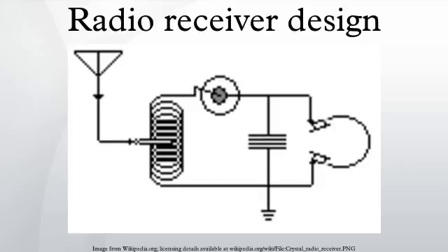Self-oscillation reduced the quality of its reception of an AM radio signal but did ironically make it useful as a CW receiver inasmuch as the beat signal between the oscillation and the radio signal would produce an audio beeping sound. The oscillation of the regenerative receiver could also be an annoying source of local interference. An improved design known as the super regenerative receiver improved the performance by allowing an oscillation to build up which was then quenched, with that cycle repeating at a rapid rate.